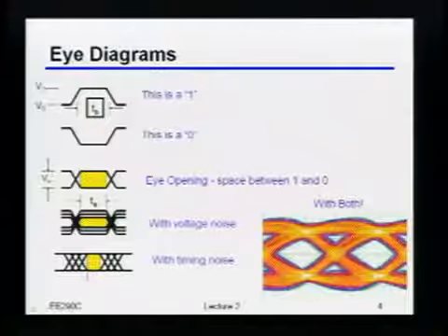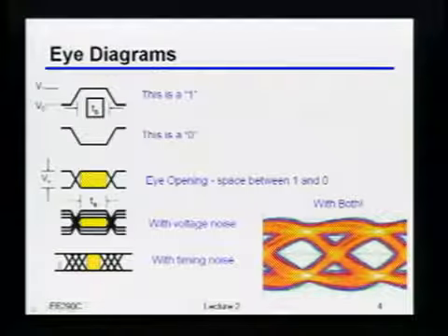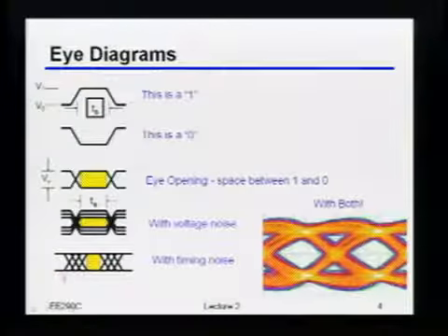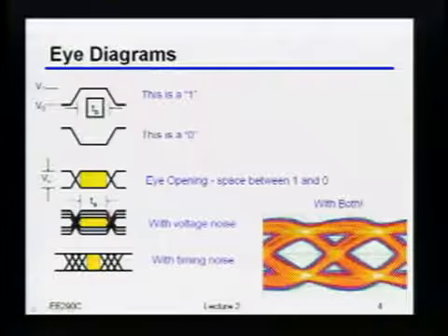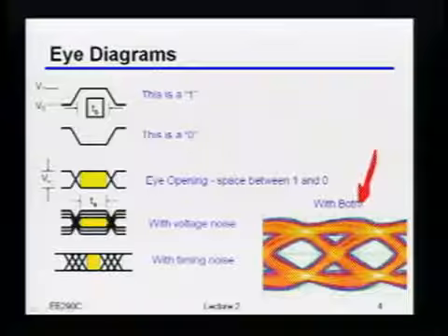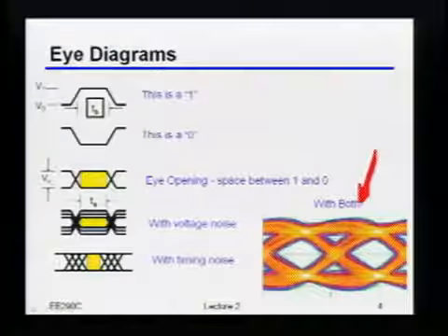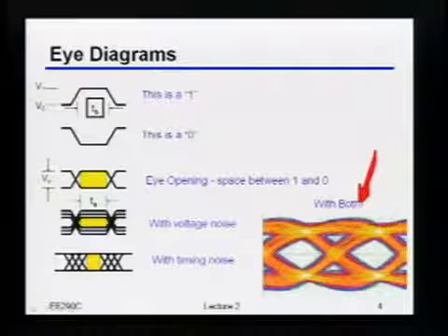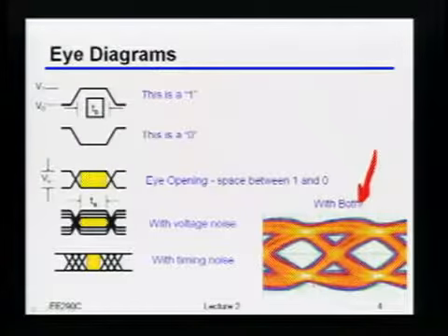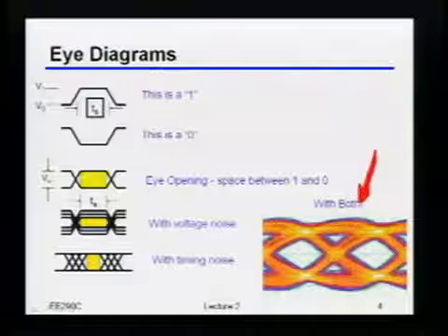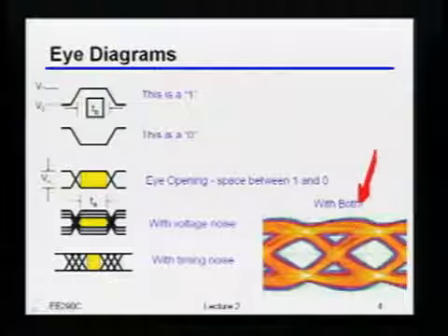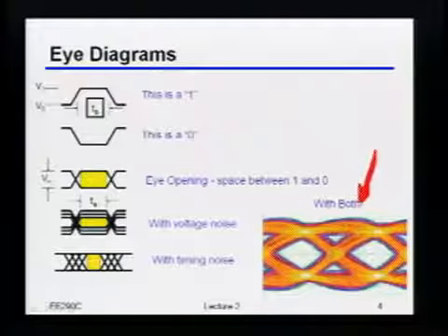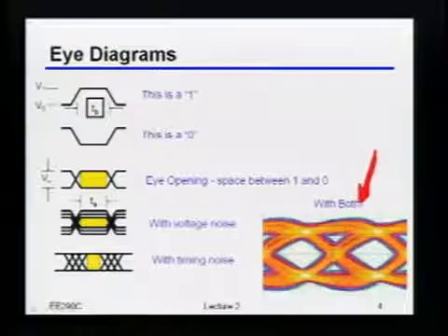Similarly, if I have noise in time, or jitter, then I'm shifting around where that actual transition occurred, right? So of course, if I have both of these things, you end up with something that looks like that, right? So it's not exactly clear when the transition in time happened. By the way, this is just an oscilloscope trace with infinite persistence turned on. So the way you interpret this is that a more yellow or white color means that there aren't as many voltage points there.